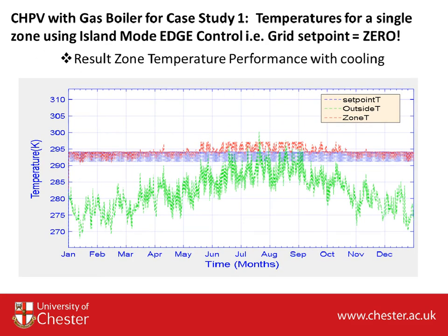Well, we could use the dynamic simulation to optimize the size of the gas boiler to meet the comfort. What also affected the sizing, surprisingly, a little bit, was actually the electricity cooling demand needed to make sure that the commercial buildings, particularly the BBC buildings at Media City, didn't overheat. So that's the power of the dynamic simulation to get your sizing right and to achieve your ideal control response.